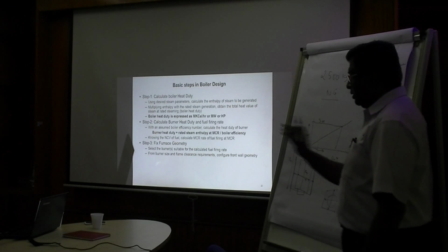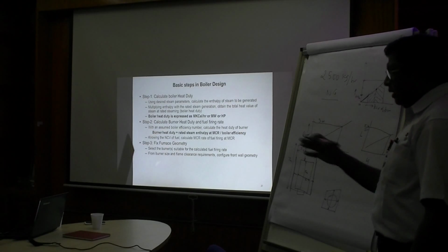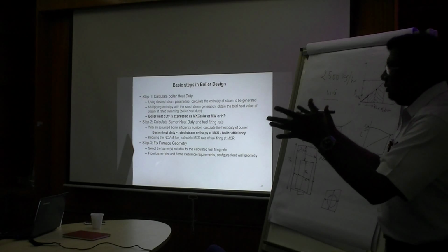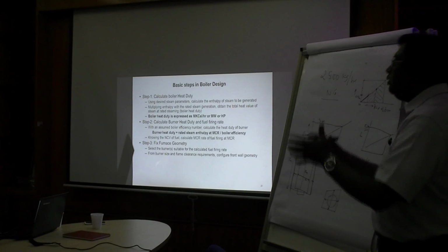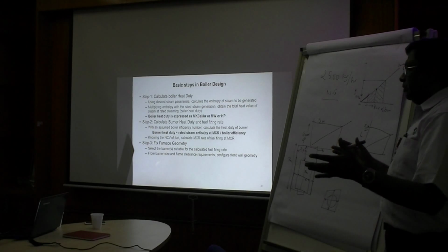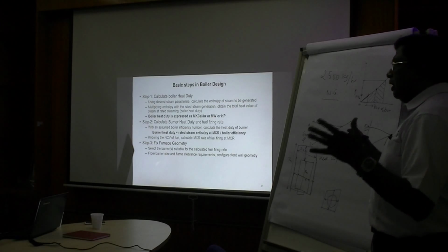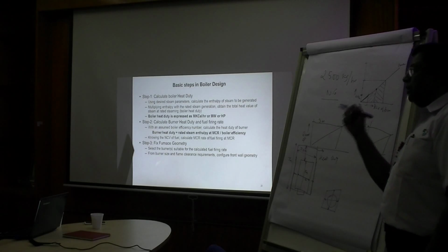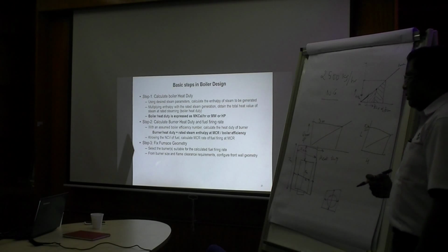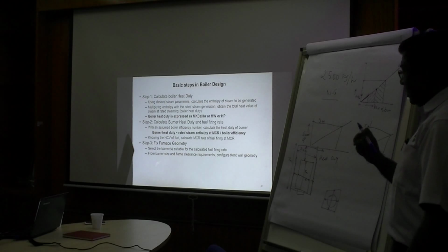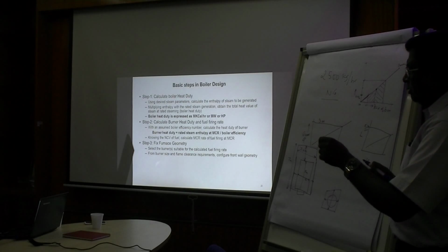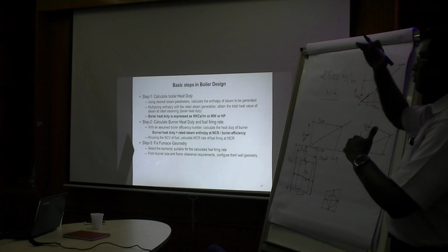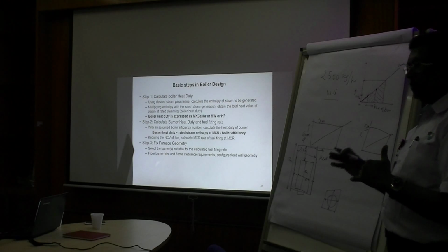That is one reason. And I already explained indirectly that if you have a very big burner, then the jerk it gives to the furnace during the first fire is also big. And then your furnace starts to shake, and how many starts you give to the burner, that many times it has gone through a mechanical impact cycle like an earthquake. So that is one criterion. Second criterion is how much turn down you require from the boiler.